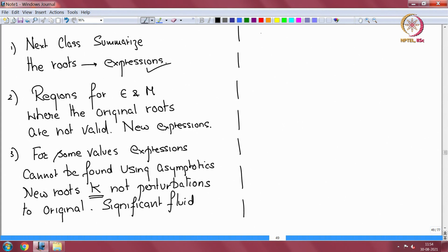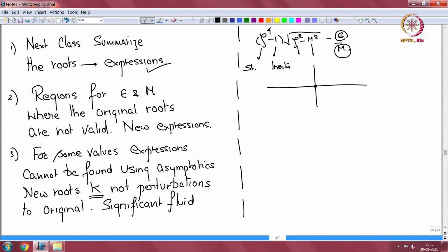Then we will examine this denominator, which I said represents structural stiffness, structural inertia and so forth. So we will change the values of epsilon and m, and we examine which of these physical factors are dominant in which regions in frequency. Somewhere structural inertia will be dominant, somewhere fluid inertia will be dominant, along the frequency axis. We have the frequency axis going from 0, non-dimensional value 1 and above. So we will see which of these dominate in which regions in frequency as we move along frequency.